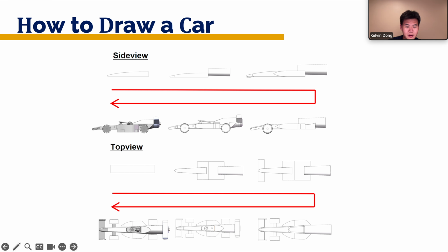Rule 3, parametric variables. Don't hard code numbers if you plan to tune them. Things like wing thickness, mounting angle, wheel spacing shims, ride height pads. Make those driven by parameters so you can change one variable and update the geometry everywhere. If you follow those 3 rules, you can iterate without fully rebuilding the car every time.